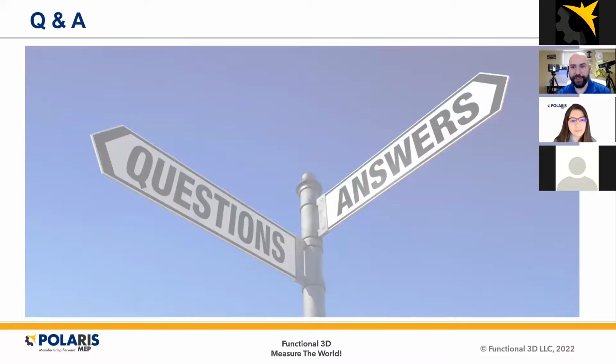Absolutely. Great question. The unit itself captures at ±1 millimeter. That's its stated level of accuracy for the LiDAR. My other unit over here also has a stated level of accuracy. We're talking about parts and pieces, so that one actually drops down to 0.08 millimeters. And that's certified. These are both certified devices. I have the certificate of quality, I guess. I forget exactly what the terms are, but they are certified, this one through NIST and that one through the EU standard.